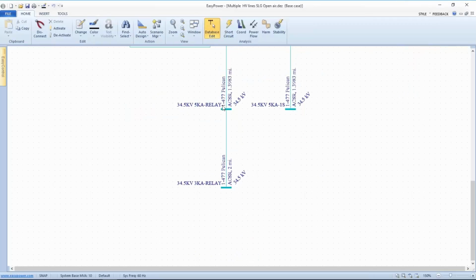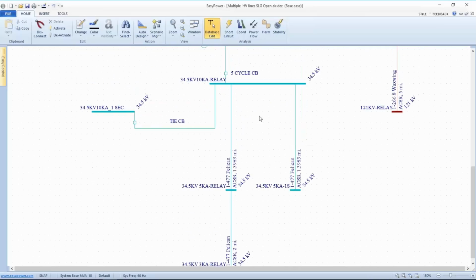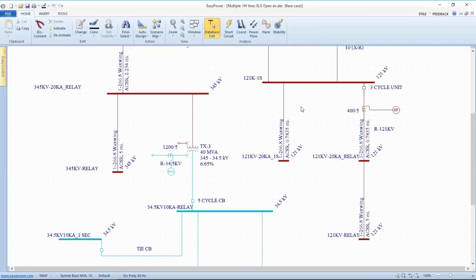So I've got two different buses here. One has the length of the transmission line set up to give me a 5,000 amp fault, and then the transmission line here is set up to give me a 3,000 amp fault. Again, I want to see what the impedance, what the trip time is, and instant energy predicted if it's protected by the relay. Okay. Same thing over here.